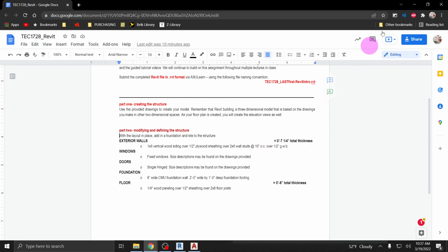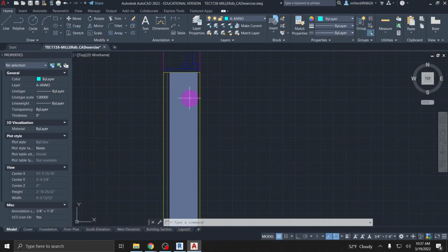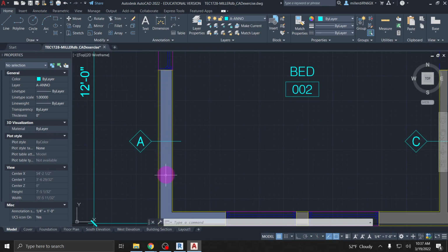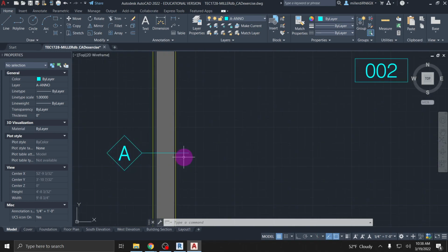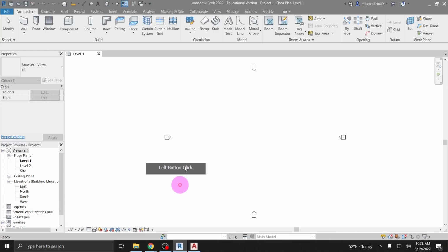And then we have our 2x6 wall stud, and our studs are going to be spaced 16 inches on center. We're not going to need to know that right now for Revit, but just always remember that our studs are 16 on center. And then a 1/2-inch piece of gypsum wallboard on the inside. So we can still put all of those different layers into Revit, and Revit will then still be able to place dimensions for things like core boundaries and keep track of all that stuff for us. But instead of having to place each one of those lines or layers individually, Revit's going to do that as we work. So if I come up here to the wall tool and click on it,